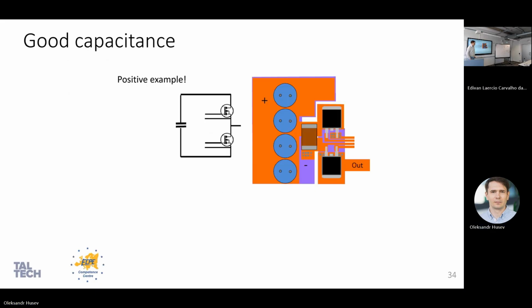So here we have so-called good and bad capacitors. Good capacitors: you have electrolytic capacitors, right? And look, orange and blue colors are different layers. One is connected to plus, another connected to negative, and you see direct overlap. Definitely this is a capacitor. Is this capacitor good? It's a DC-link capacitor, right? So this capacitor is good because by definition it will keep energy inside the PCB between layers. No questions about it.